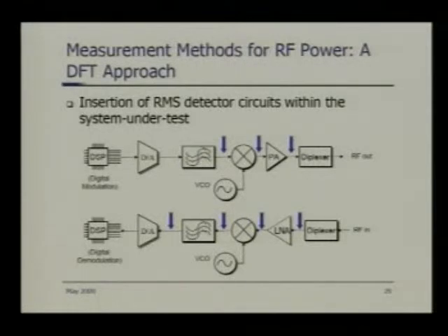But there is another method, which is the broadband method, also called the RF detector method. I don't have the slide over here, so let me describe. What you do is you have a detector, like a diode detector, or a transistor amplifier detector, to square the waveform and take the average of it and take a root of it. So basically it's an RMS detector.